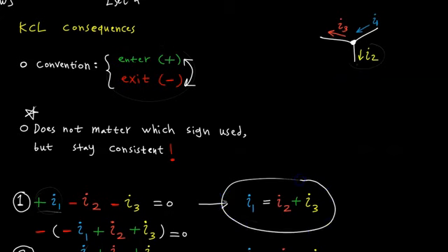This is an important way of writing this because it's an alternative way to represent KCL. Instead of saying, okay, we have n currents, so let's just go ahead and sum all the currents, we are now saying, okay, this current is entering this node. The only other place it can go from this node is through I2 and I3. So the sum of the two currents I2 and I3 must equal what initially came to the node from I1. So this is a very important note that we're going to use, and we're going to use this way of writing KCLs to quickly go ahead and analyze circuits.